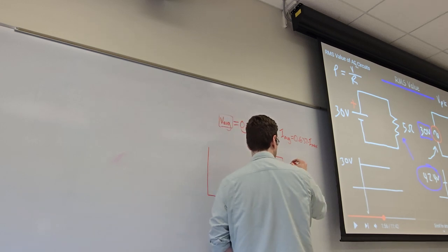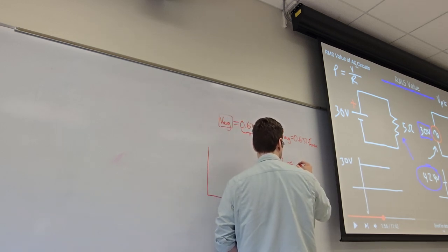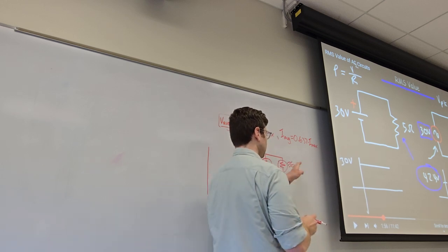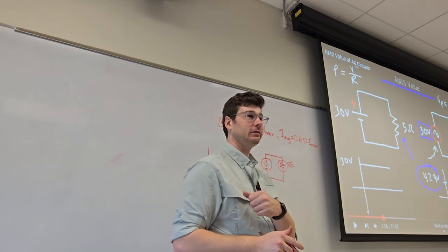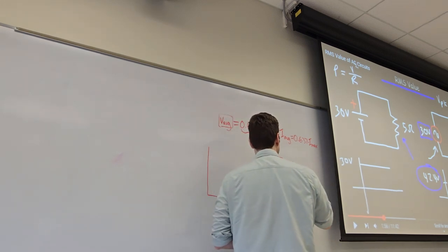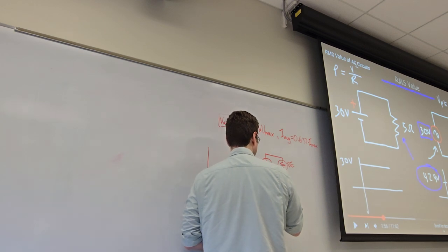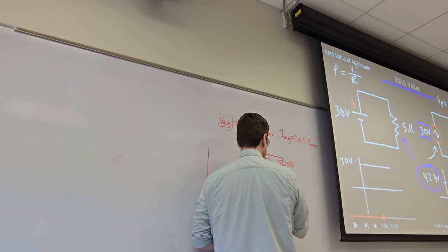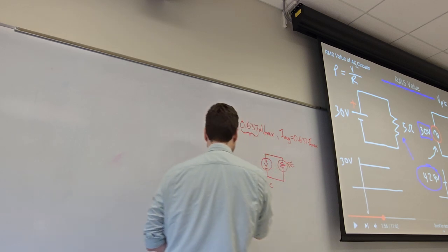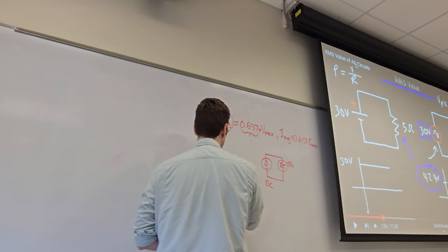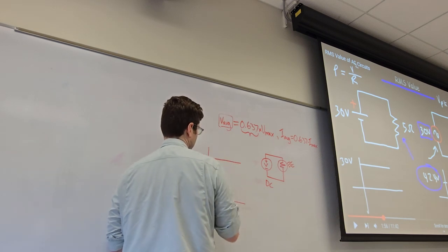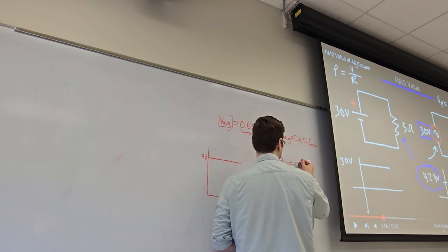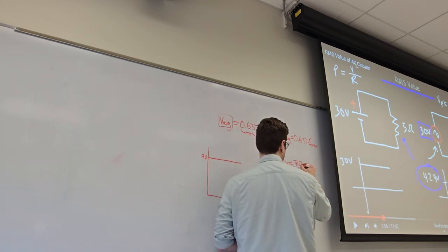Ideally, we're going to measure the heat coming out of this resistor. How much energy we are putting into this resistor can be measured in a temperature. How hot does that resistor get, essentially? So we want to understand what voltage we need to heat it up. We use some DC voltage that looks like this. Say we put 9 volts on there, and at 9 volts, we get 9 watts of heat out.